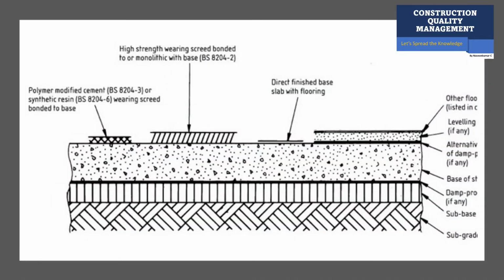Now what is a screed? Screed is a mixture. Sometimes it's a mortar, sometimes it's a concrete, sometimes it's a self-leveling compound. We just add the water and pour it, and it will level itself. There are a variety of screeds and variety of usage of the screeds, which we will understand. The basic meaning of screed is a leveling course or a sandwich course between our existing mother slab, which may be a grade slab or a floor slab, and a flooring. Sometimes screed itself will be used as a final flooring.